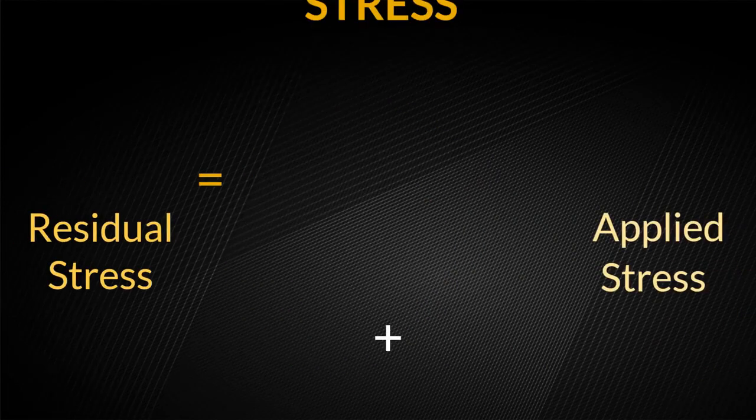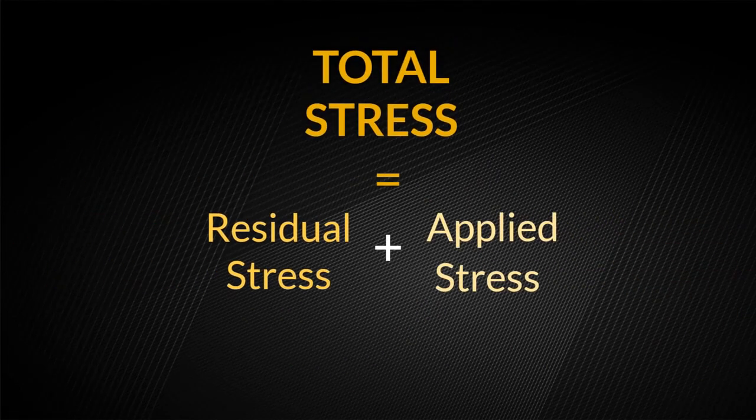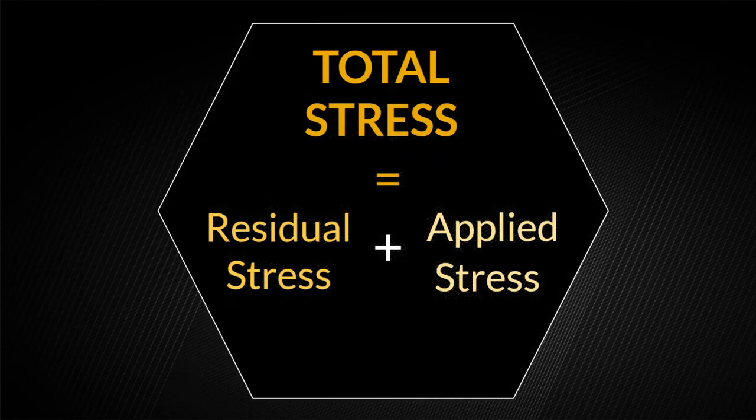We must also consider the applied stress in a component. The applied stress could be of a similar magnitude as the residual stress, making a significant impact on the part during service. The total stress is equal to the residual stress plus the applied stress.